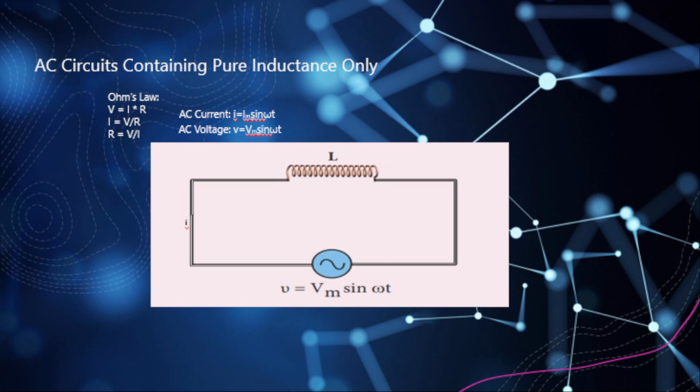I do want to mention one commonality we will find in our discussion here is also found in DC motors, wherein the coil of a motor is turned, a magnetic flux changes through the coil, and an EMF is induced. Now, Lenz's law tells us the EMF opposes any change, so that the input EMF that powers a DC motor is opposed to the motor's self-generated EMF or back EMF.